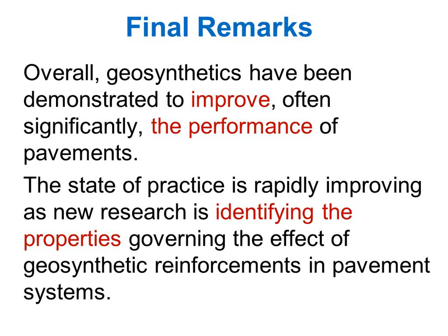It's an NCHRP project. Have you heard about GRS-IBS, Geosynthetic Reinforced Soil Integrated Bridge Systems? We are constructing a mega pullout box, not with transparent soil, but with a transparent sidewall. So we will do pullout tests and we will not see the deformation of the grid, but the intention here is to characterize the shear band that develops under actual aggregates.